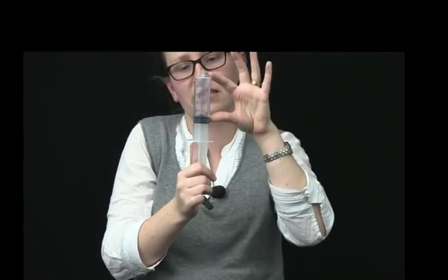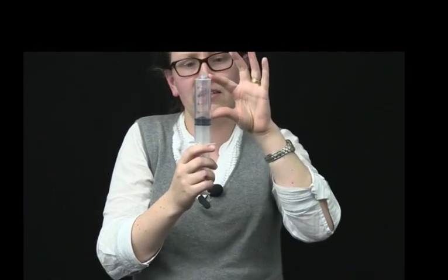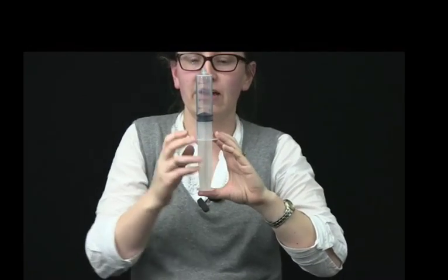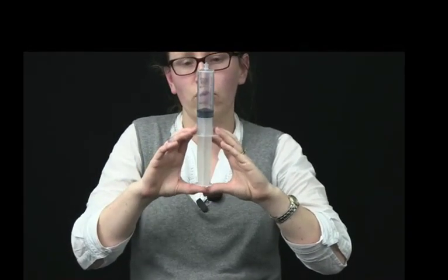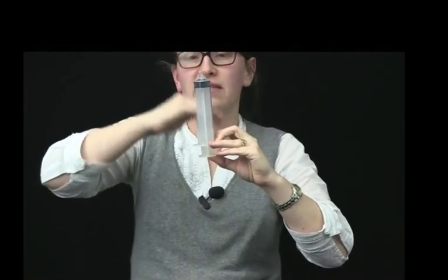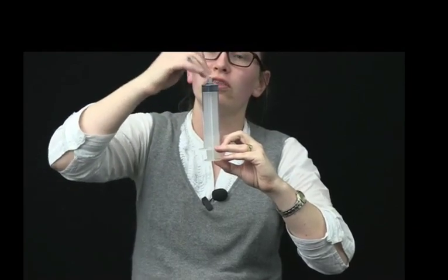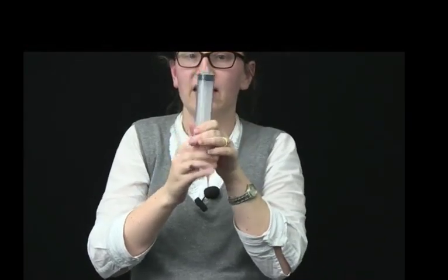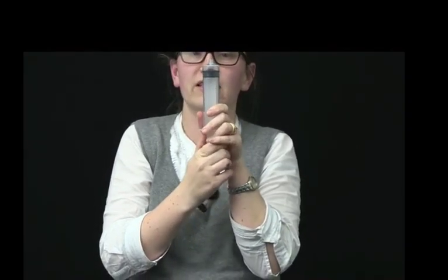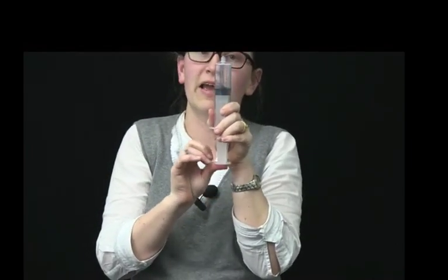So now that this is expanded, this cylinder is full of spent fuel and air. So finally, to complete the cycle, the car does a bit more work on the engine. It compresses the cylinder, the piston, and that releases all the spent fuel and the air out of a release valve up the top. So we're now back to where we started. It can pull in another fuel-air mixture, compress the fuel-air mixture, there's a spark, it expands rapidly, releasing energy, and then finally it empties out again.